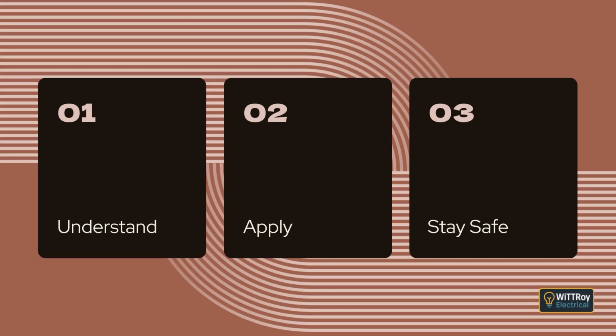Clause 3.9.7.6 Undercarpet wiring systems. Undercarpet wiring may be used only as a floor-mounted system, and only in areas not larger than 1 meter by 1 meter. The system must be installed according to the manufacturer's instructions. Systems of different designs must not be interconnected unless the manufacturer specifically permits it.